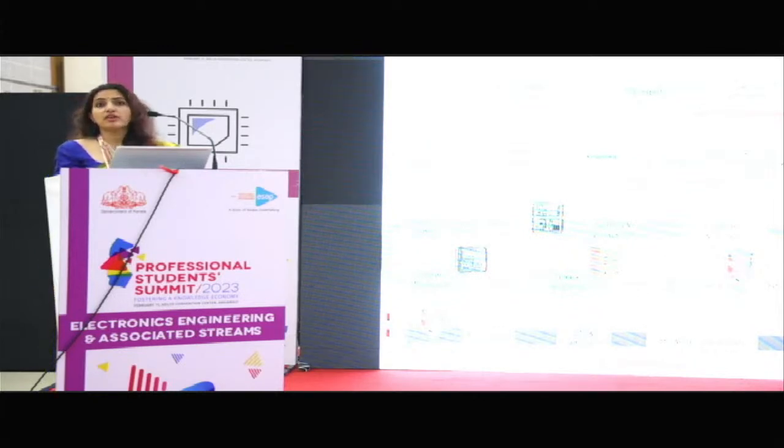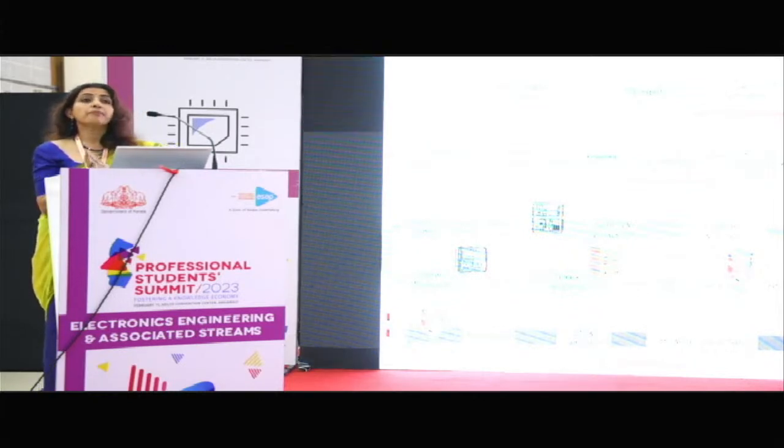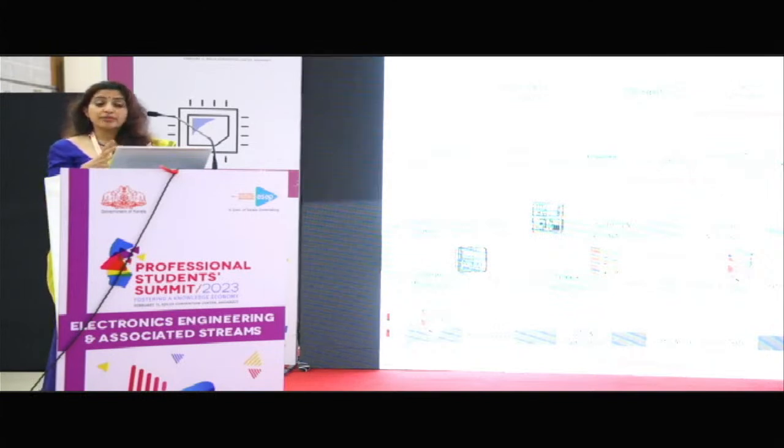And there is a process called screening, which is not in the commercial sector. There is a test plan, and we subject all these components to a series of tests, in fact. If the component fails, there is a certain fraction, and if it exceeds that, we'll reject the whole lot. So it's very expensive in the space industry to get the component correctly, and to implement that is a whole expensive affair. Now finally, if everything is okay, then we'll implement it in the package.